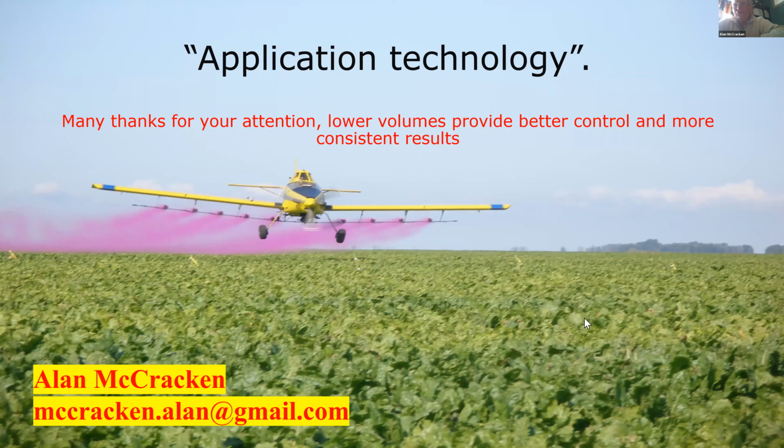Dish soap will reduce the surface tension of the liquid. That's why it helps to wash the dishes. And what happens when you do this, and we've tested all these options in Brazil, dish soap, also soap to wash engines, it reduces the surface tension, which means that the equipment on the aircraft will produce a smaller droplet, but unfortunately, the dish soap will not protect against evaporation. So we will increase evaporation loss. We will increase drift. So in essence, I do not recommend using dish soap.